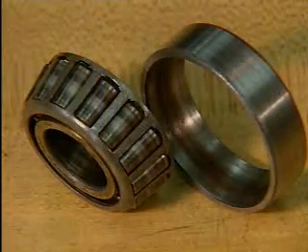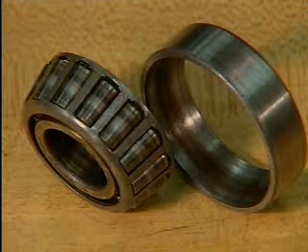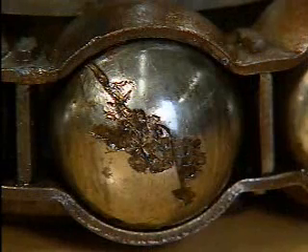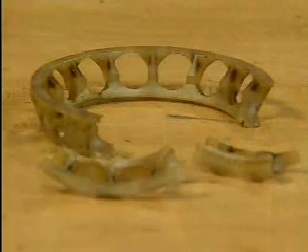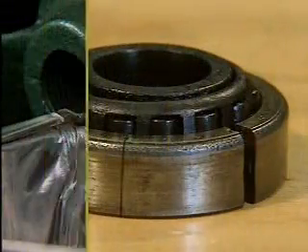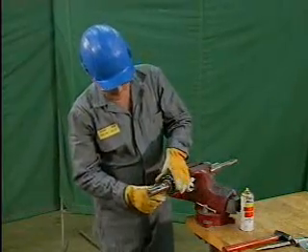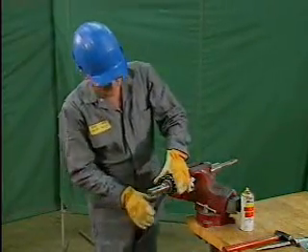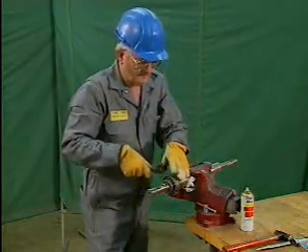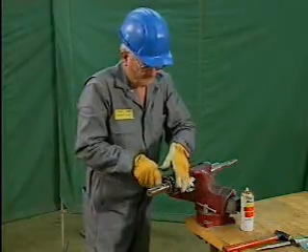This evidence may include burn marks, which are blue or brown marks on the rolling elements or the rings, spalled areas, which are places where the surface of the metal has flaked away, a bent or broken retainer, cracks in the rings, and discolored lubricant. If the bearing failure is unusually severe, all of these signs could be present, but not all of the signs are necessarily present with each type of failure.